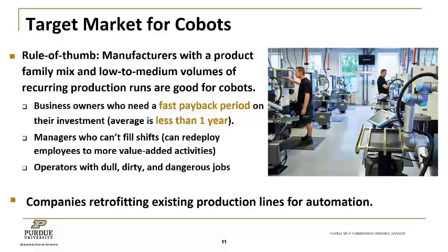But again, because of the grippers, if you're not making it do different tasks, if you've got one gripper and you're able to handle, say, a machine tending operation with it, you can probably handle multiple different parts with that one robot, just in the fact that it's picking up different, say, blanks and putting them in the machine and just running different programs on the CNC machine. So these robots really can handle a wide variety of parts. It just depends upon your specific application.